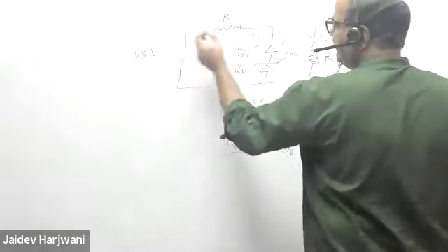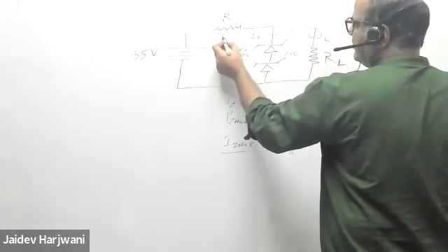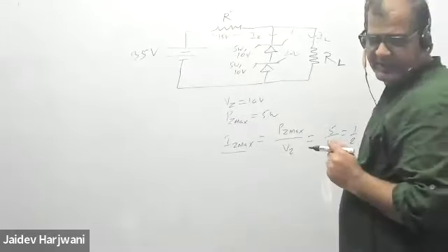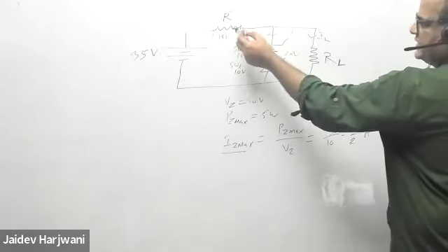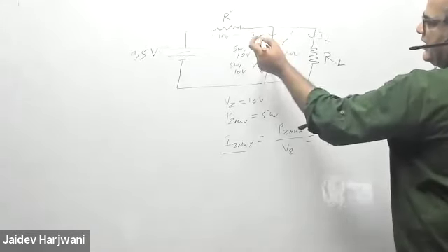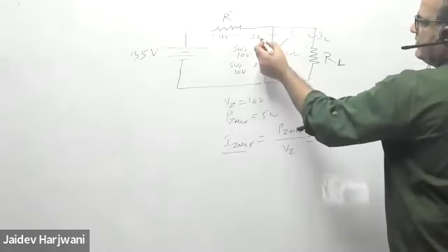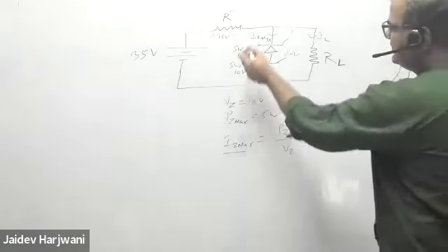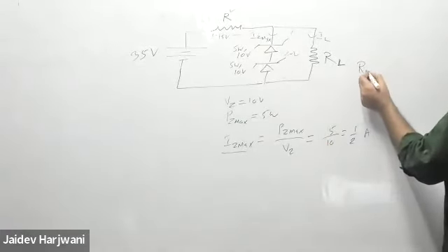Here voltage is 35 volt. So voltage by the voltage divider, here voltage is your 15 volt. Now voltage is fixed here, but if I start reducing the value of resistance, what will happen? Current will become, at a particular value, IZ minimum, my current will become IZ max. So let us find now what is the value of this R minimum. So I can find my R minimum.